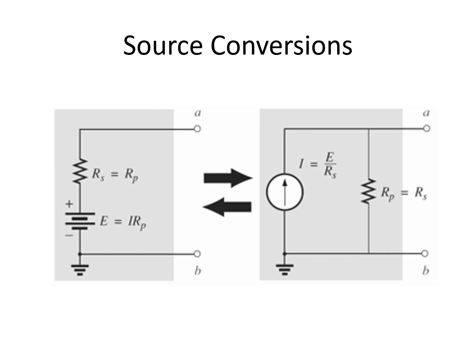Or vice versa. If we have a current source, we can solve for the voltage. Voltage is I times R, so the voltage here is equal to I multiplied by R_P. And the I here is equal to E divided by R_S. That is what we call source conversions. Usually, circuits that can easily be solved using a voltage source are given with current sources, or vice versa, so you can just convert them. That is the relationship, and that is how you are going to convert them.